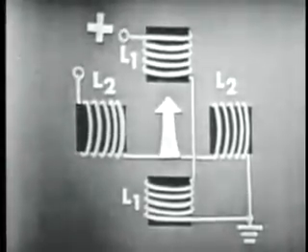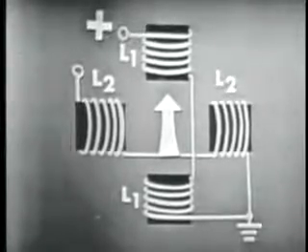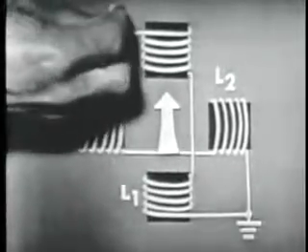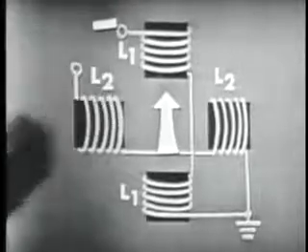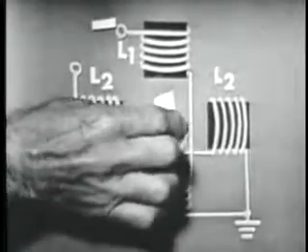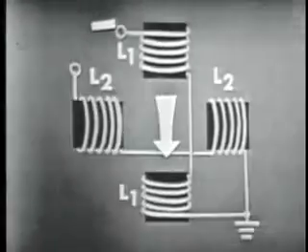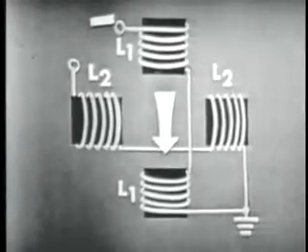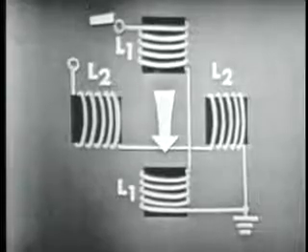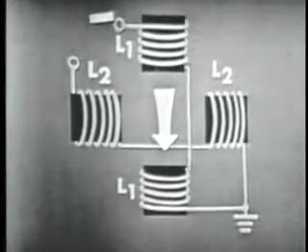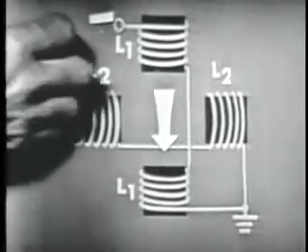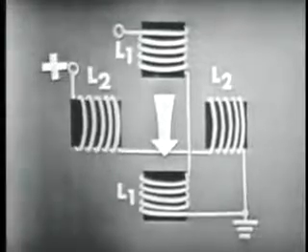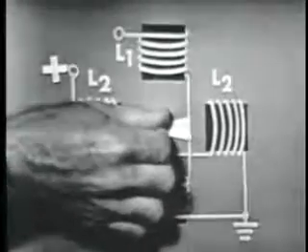Another good point is if we reverse the polarity on L1, make this a negative, in other words, we'll, of course, reverse the direction of the magnetic field produced by L1. And the rotating magnet will again line up with this magnetic field. Now, the same thing, of course, applies to L2. With voltage applied only to L2, we'll produce a horizontal magnetic field, like that.